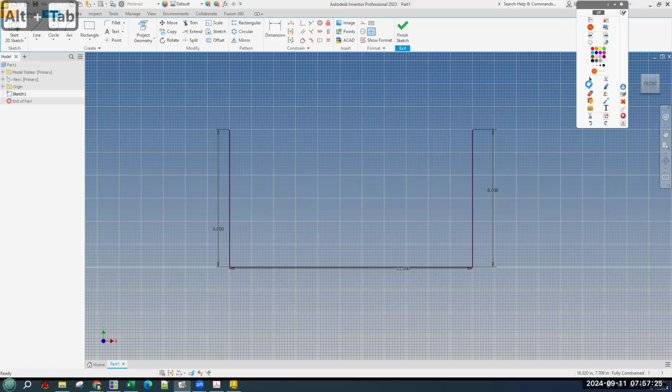Let's go like this, and we're back here. Okay, yeah. Keyboard shortcut L is straight to the line tool. If you type D, it jumps to the dimension tool. Those are good, useful keyboard uses.